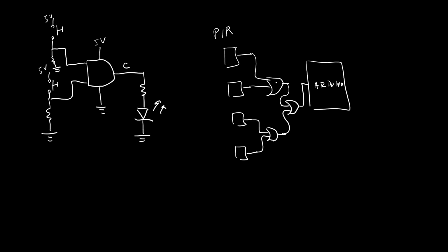And rather than using 3 separate gates for that, you can also buy integrated circuits that have multi-input gates. So for example, an OR gate with 4 inputs, where you're then going to have a much bigger truth table. I'm not going to bother drawing the whole thing out here, but say inputs A, B, C, D, and output E, where now the output E is going to go high if any of these inputs are high, and you would have the corresponding truth table.